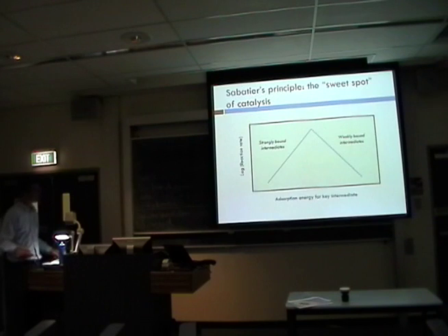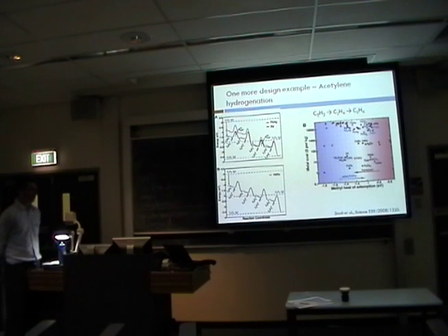Let's see. So actually, I forgot I had this example in here. So this is a fairly recently published example of using this kind of strategy. This is for a refinery kind of application. So prior to ethylene polymerization, you have some acetylene in the feed that actually screws up the ethylene polymerization reaction for making polyethylene. And you want to get rid of that acetylene, but it's small amounts of acetylene that are floating in a sea of the desirable feed, which is ethylene. And so you want to selectively do this, but not keep on adding hydrogen to make that.